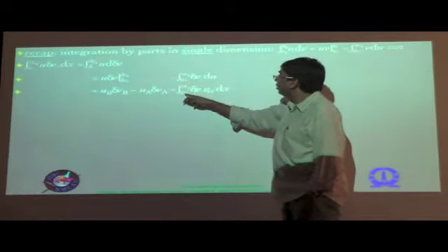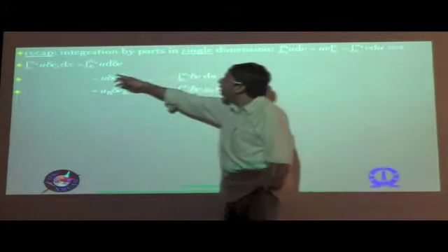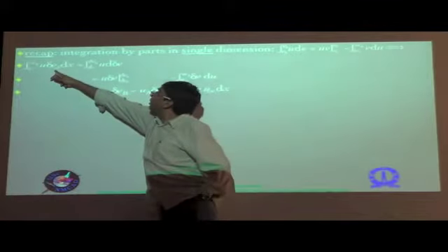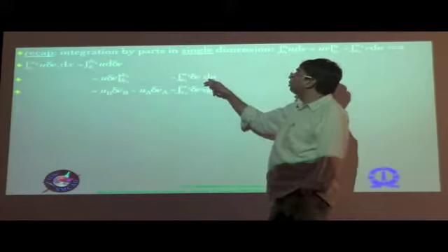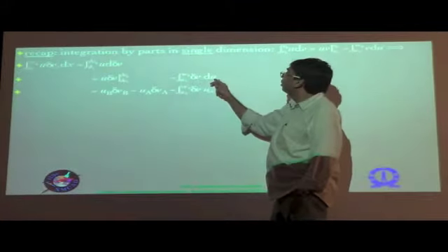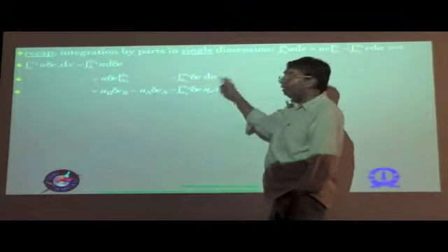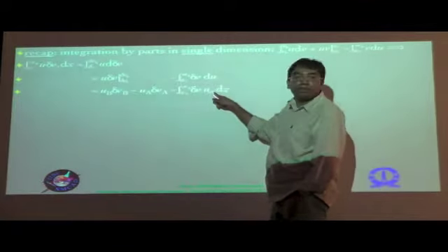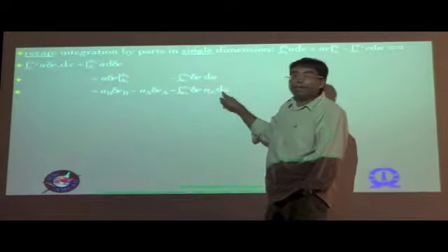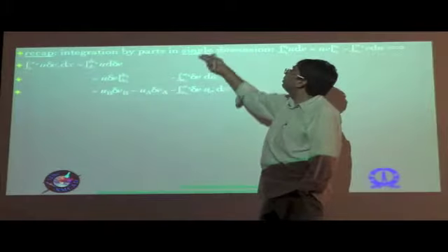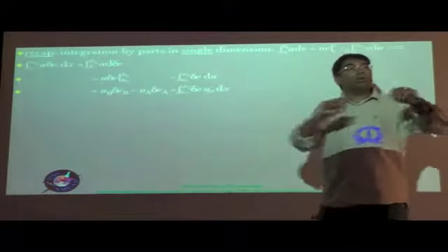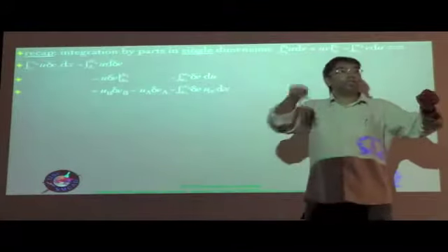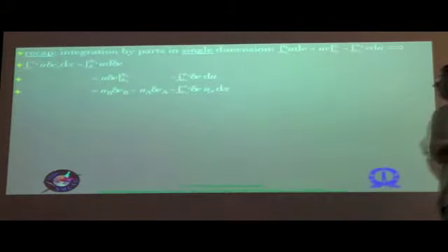Similarly, this integration also, just like how you took this derivative with respect to x out, you can reintroduce that with respect to x. Instead of delta v du, you can make it du by dx into dx, and so that's basically u comma x that you have over here times dx. So this is something which is very familiar from the single dimension, that we want to extend to 2 dimensions, because the integration that we have now is not over a single dimension but over a cross section, which is a 2-dimensional area, right?